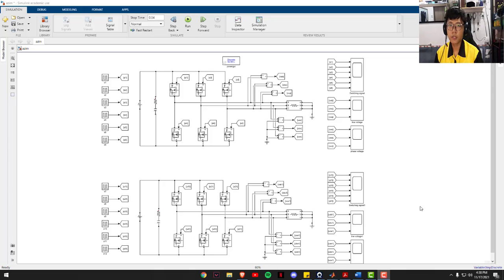So today I will explain lab activity number 3, which is to modify the pulse generator to generate the PWM waveform with the condition based on 120-degree conduction mode, and to find a few parameters needed for this lab. As we can see here, the top one is the 180-degree conduction mode, and the second one is the 120-degree conduction mode. The circuit in MATLAB Simulink is approximately the same, but there will be a slightly different value in the pulse generator. I will show in detail later.